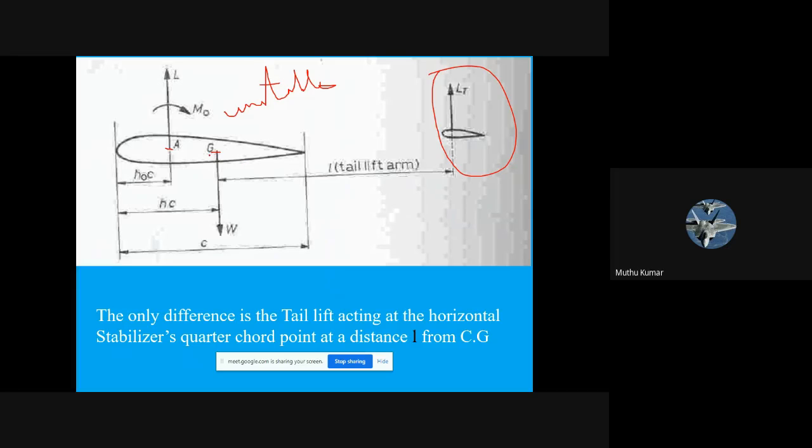Yes or no? Because the weight CG is behind the aerodynamic center. Okay, but this is a practical configuration. CG usually lies at around 50 to 60% of the body, that is reasonable. Okay, if that is to happen, I need to add a tail.